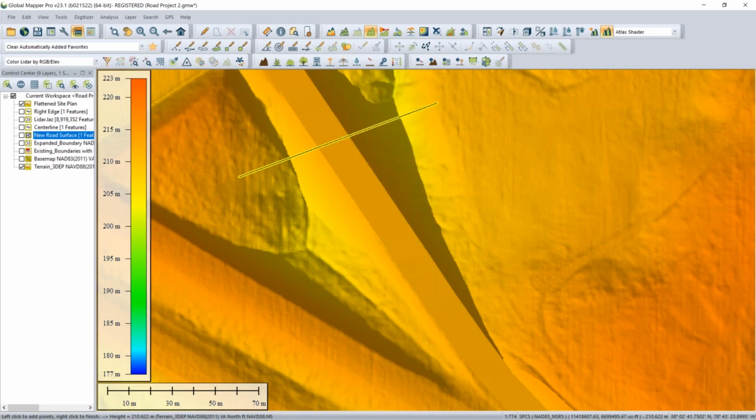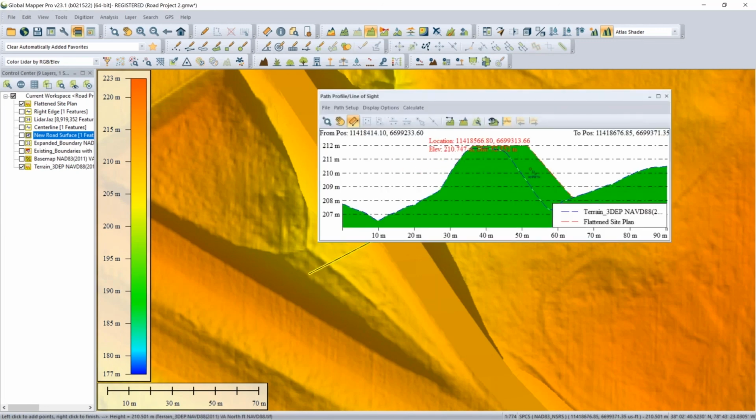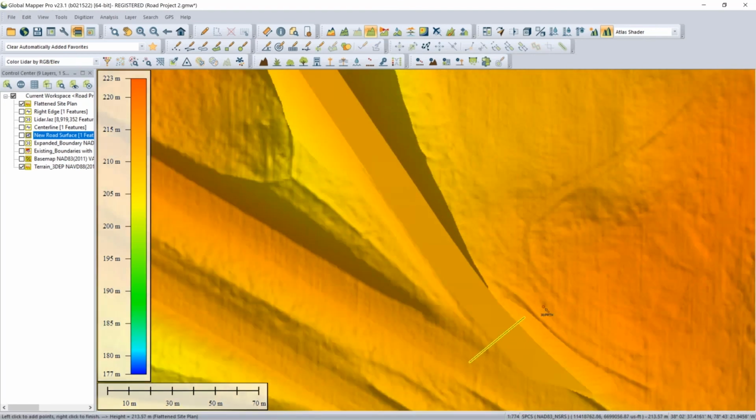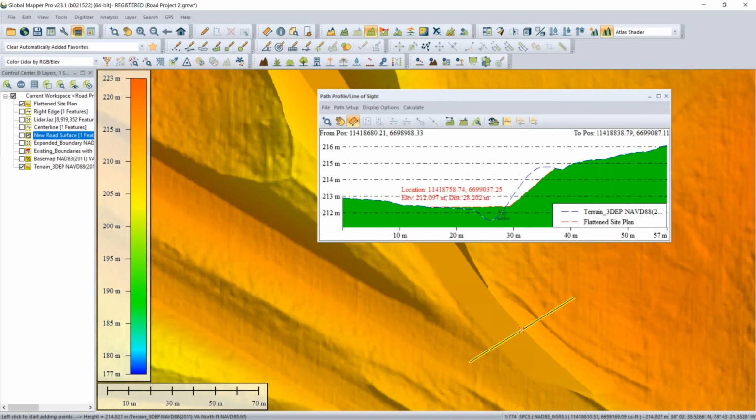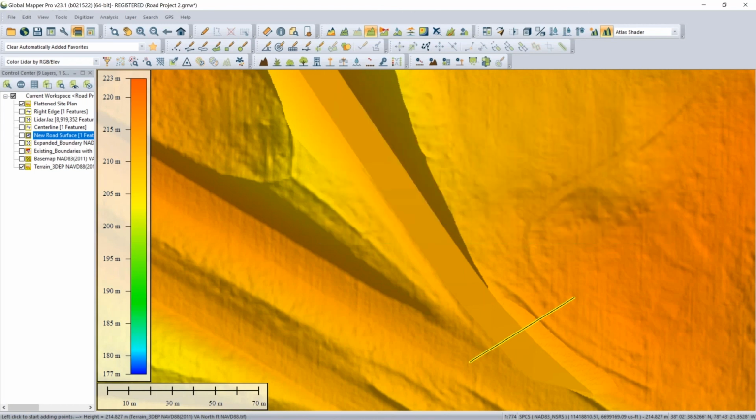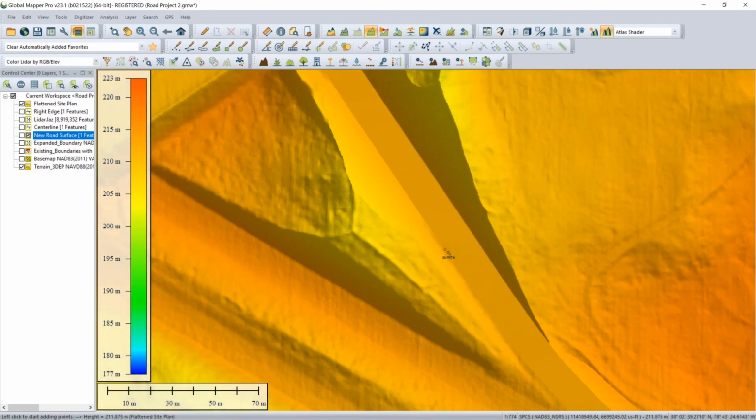And again, we know based on the calculation we applied previously how much of this material we're going to have to remove, or how much we will need. I think if I go a little further to the south, we're going to get a little bit here where we actually need to adjust our embankment. We need to move material to accommodate that wider shoulder there as well. So we can get those visualizations. We could generate contours. We could visualize this as a 3D model.